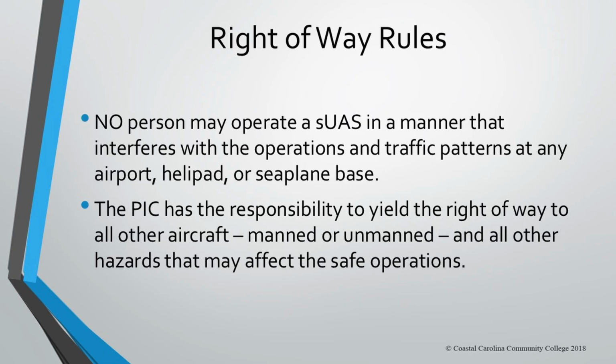Right-of-way rules. No person may operate a drone in a manner that interferes with the operations and traffic patterns of any aircraft, helipad, or seaplane base. The PIC has the responsibility to yield right of way to all other aircraft, manned or unmanned, and all other hazards that may affect safe operations.